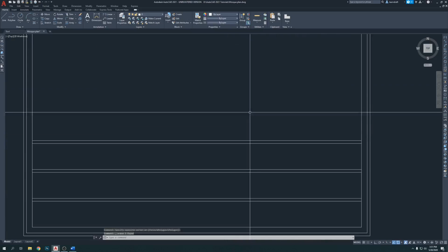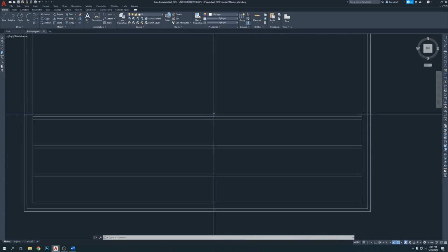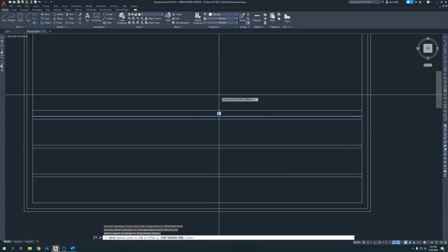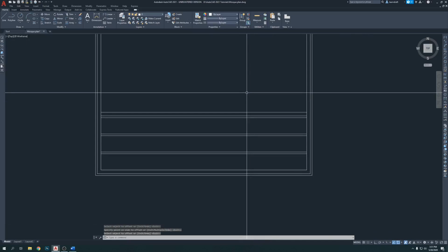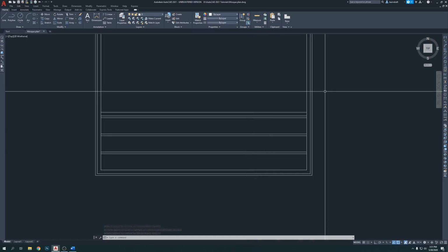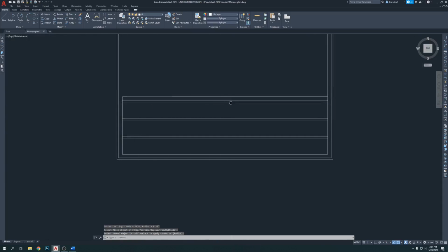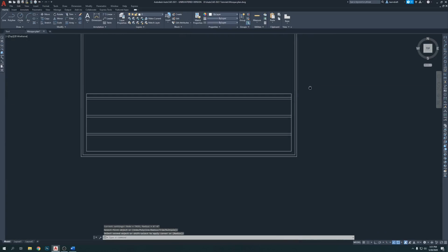Now what you're gonna do? You need 1 feet here, like how you have 1 feet everywhere, like this. Offset. Enter. 12. Enter. Click here. Click there. So the line is, we have the 1 feet line surrounded. So we're gonna make it fillet. Enter. This one with this one, and here. Enter. Click here. Click there.